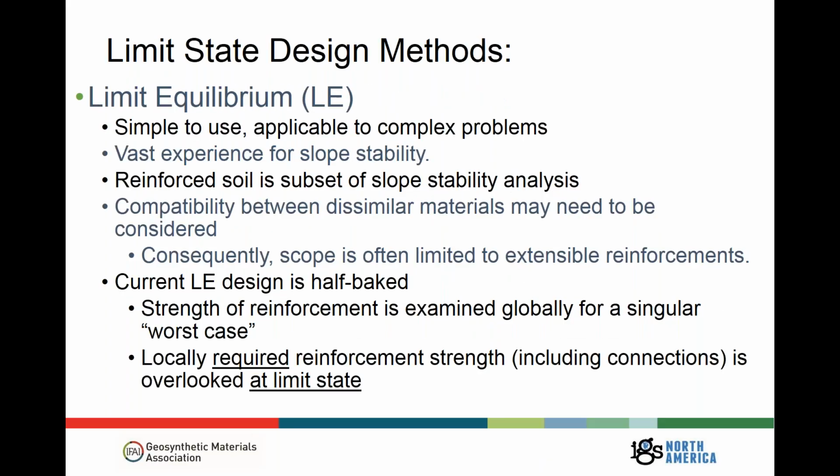So let's talk about limit equilibrium, which is going to be the focus of today's webinar. Limit equilibrium is pretty simple to use. It's been applied to complex problems, and we have vast experience using it. It's been around for quite a long time, in fact, the 1700s, and for the most part, it's basically just basic statics. Reinforced soil is a subset of the slope stability analyses that limit equilibrium methods are commonly employed to, and limit equilibrium methods, or LE, can capture the effects of reinforcements at the strength limit state.